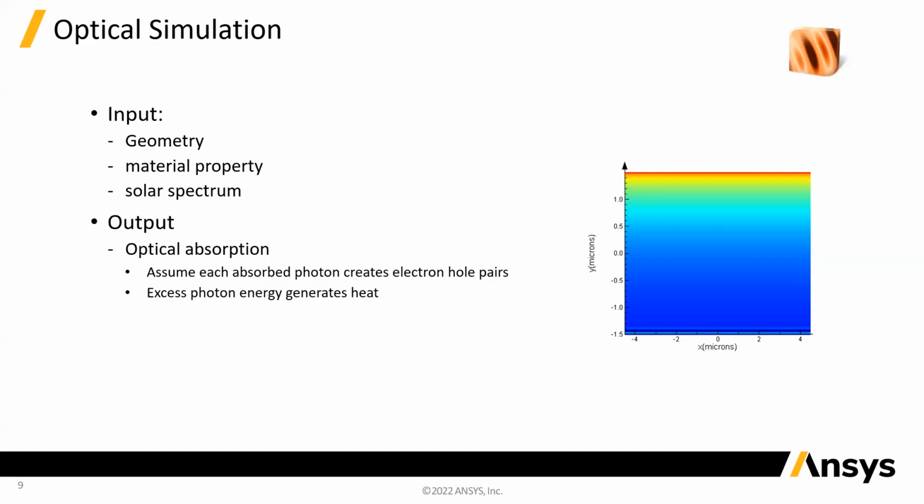And then you go from one time step to another, and every time step you solve Maxwell's equations and figure out the electric and magnetic fields. And once the whole simulation is done, you can go back to your simulation result and see how light propagated through your entire device as you went through each step of time. And based on that, you can then figure out how much of that light got absorbed in your structure.